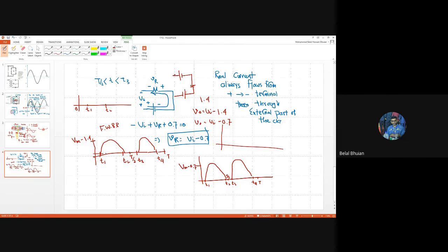So that means we have to give quite a large amount of voltage to the diodes. The diodes take away 1.4 for the full wave bridge rectifier. Also, it takes longer time to turn on, because you have to conduct D1 and then D2 before it starts. Since there's only one diode to conduct here, it takes a relatively shorter period to turn on, and it takes relatively twice as much here.